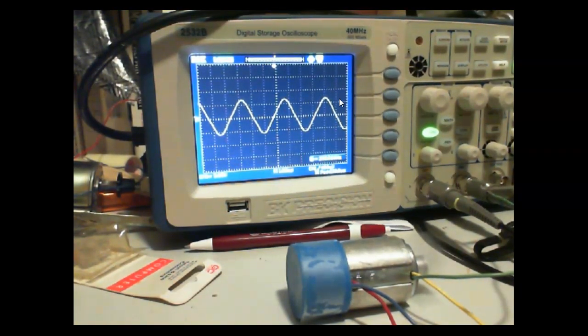So we have DC tachs, which are still out there. You can still buy them, of course, but in popularity, we're moving over to AC tachs. This is why they went to an AC generator in your car, which we call an alternator, because AC generators are better than DC. They last longer. We're not trying to take the power off something that's spinning. We're taking the power off something that's stationary. We still have what we call slip rings, where we bring the DC voltage into the spinning rotor so we can actually control the strength. But AC alternators last a pretty good long time too, and they cost a lot of money too.